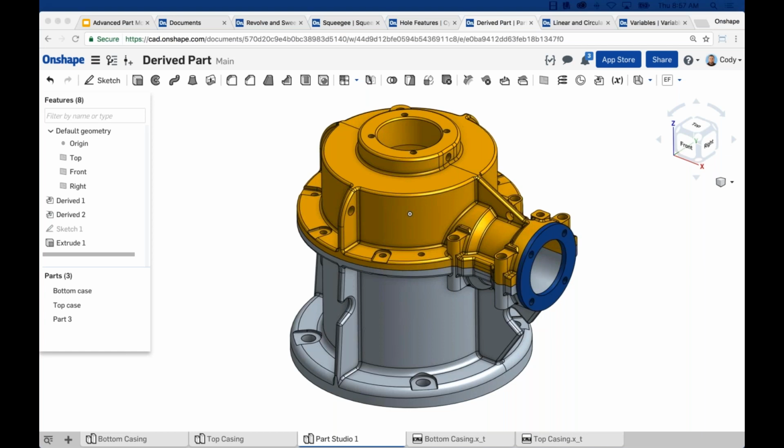I think that they meant the tap drill goes through and tap from each side. I see. I think I understand in that scenario. And I think it's going to be a limitation. You can define a tap in a single direction, but I don't think you can say tap both ends of the hole. In this case, I would just put a tap drill hole through the whole thing.